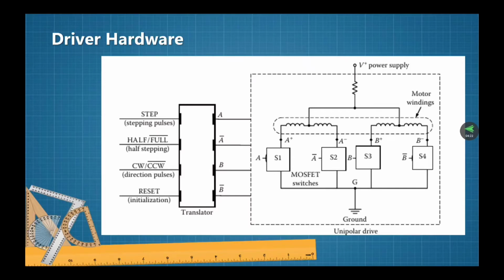In a drive module, there are several pins, some of which are connected to the motor controller or the computer, the driver inputs, and some connected to the motor leads, or the driver output. There are the other pins which correspond to the DC power supply, and then common ground, and then various control signals.